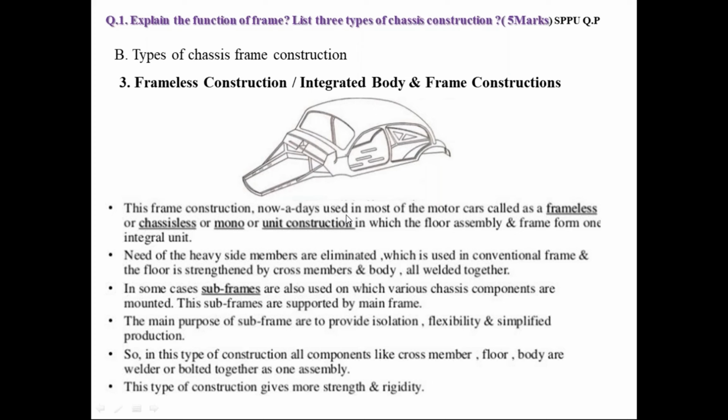The repairing of the frames, if we had made an accident with this type of structure, repairing is not possible. So generally, we go for small cars with this type of structure, that is the frameless type of structure, in which we have an integrated superstructure or integrated body, we call it. So the same thing is mentioned over here. So different heavy structures will have the advantage of reduction in weight. So this total frameless, subframes may be attached to this as well.